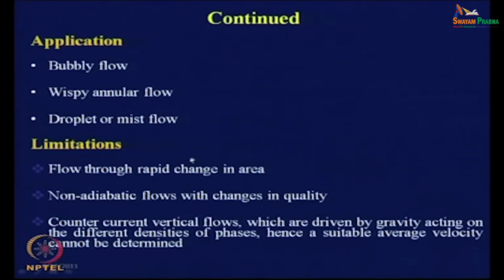I have just mentioned this, but I had not given the specific examples: flashing of steam water mixture through short nozzles and orifices, bubbling in superheated liquid or supercooled vapor condensing in high velocity stream, and particles of solid propellant burnt in nozzle of rocket engines. Under these situations, there is rapid acceleration, rapid pressure changes, and we cannot use it.